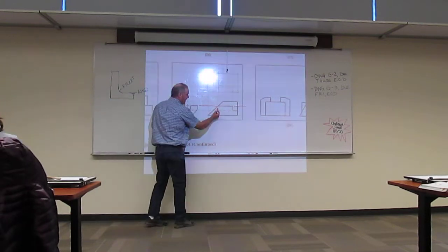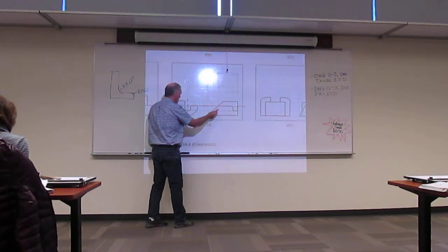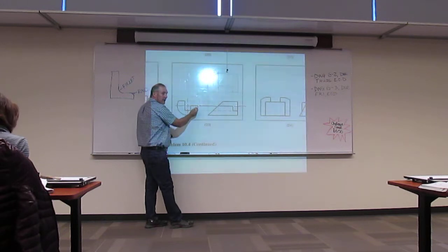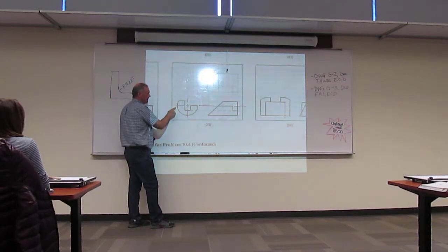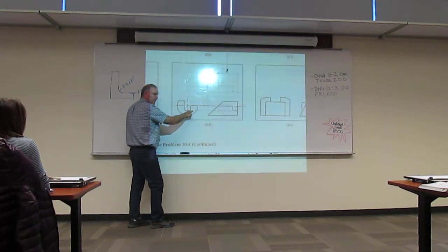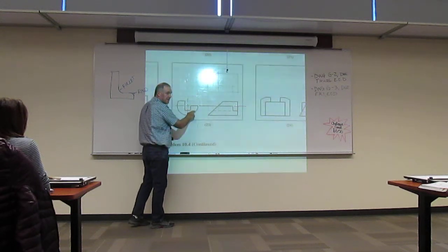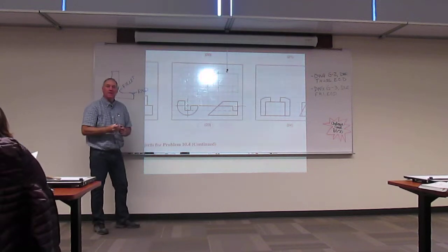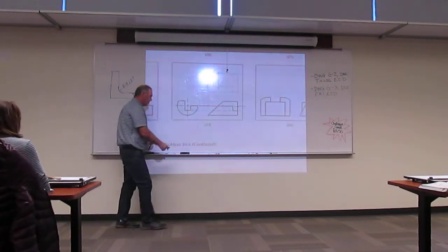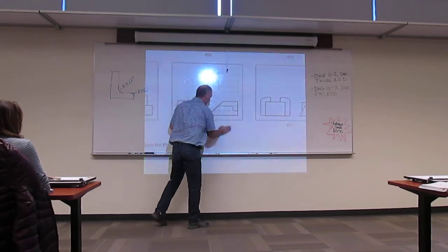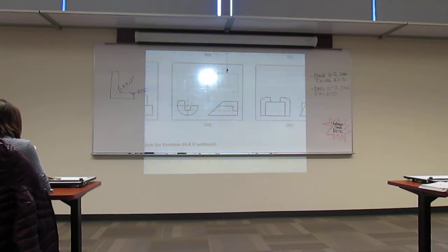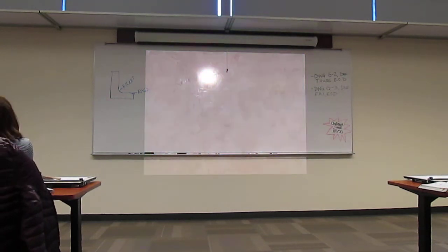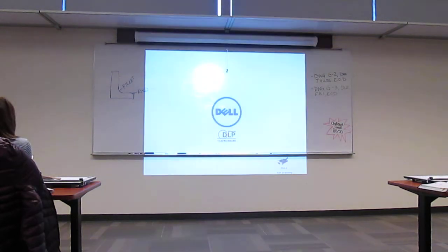So this cut right here happens right on it. So notice I'm halfway up, I'm right on the cylinder. This cut right here goes past the limiting element. It's on top. This cut here is before I get to the limiting element. So you're going to want to look for those items as you project these. Usually you're checking that quadrant location, and that will tell you how things are going to work. So with that, let's jump to the computer.